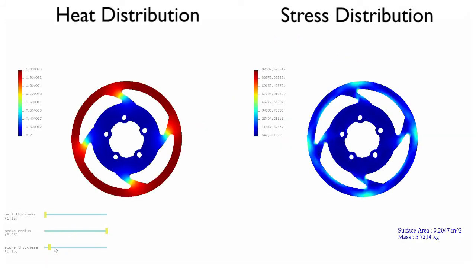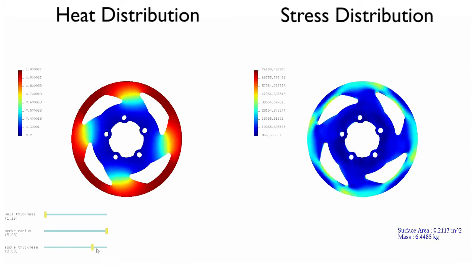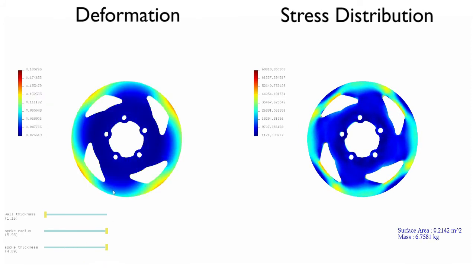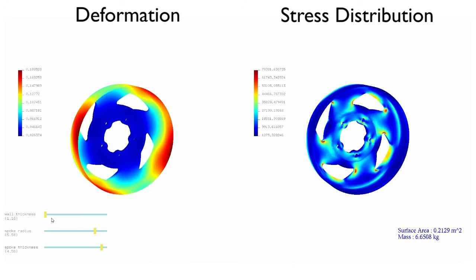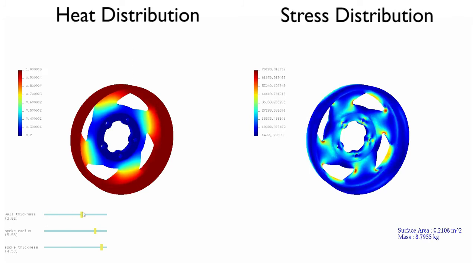And this example shows a thermal expansion that is coupled with a stress from the brake hub. The pre-computed simulations include the heat distribution, deformation, and stress. The heat source is uniform on the inner wall, while the forces from the brake hub are directional. Notice that as the thickness increases, the deformation on the rim becomes more uniform, since the impact of the heat outweighs the directional forces.